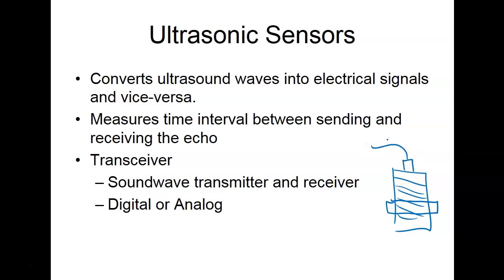And then what we can do with our sensors is set the span. Now, what's the span? It's the distance between what you're trying to sense. If you've got a compressor at your house, or if you've seen compressors, those have a span. They usually turn the motor on at around 70 psi, and then it runs until it gets up to 100 psi.